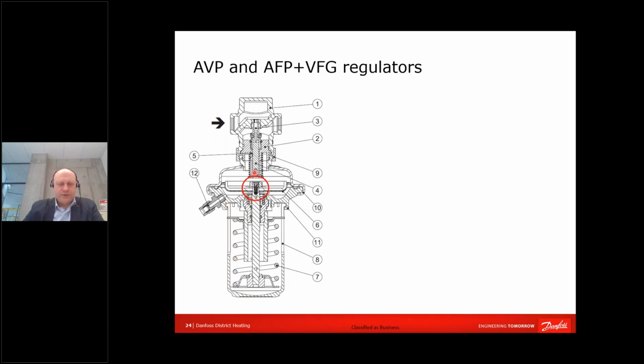A unique feature of our products is that we have a safety valve, which opens on differential pressure increase above 2.5 or 3 bars. So if you are pressing larger pressure to the plus side, a small safety valve will open and let water go through and will protect the membrane.